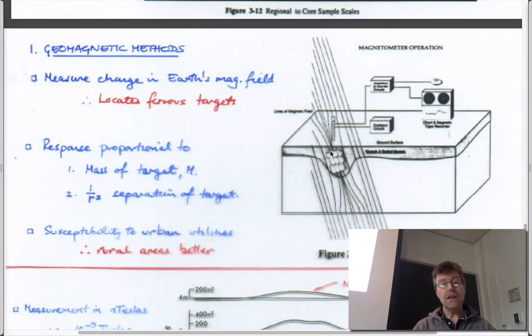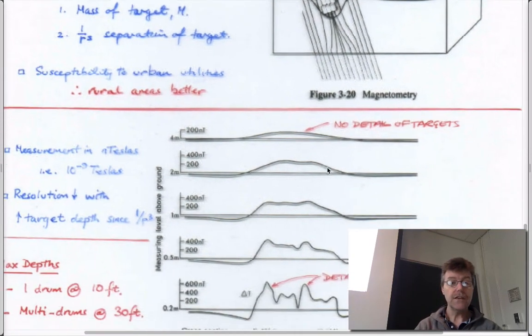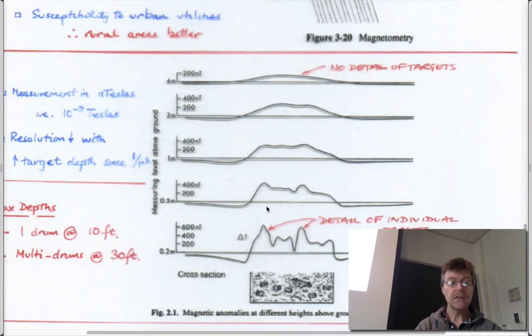If these are lines of equal potential, you can run a section by taking an instrument that you physically place at a variety of different locations, and take a measurement at each location of the strength of the magnetic field, and its orientation maybe. Then if these lines of force are bunched up to go through these 55-gallon drums which exist below the surface, you'd see a change in the strength of the field as you go across here. And I think that's exactly what this is showing here.